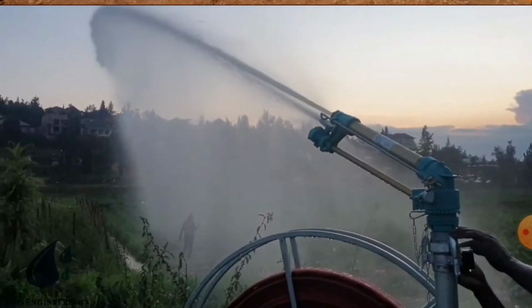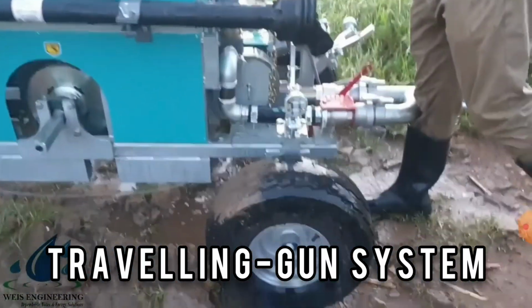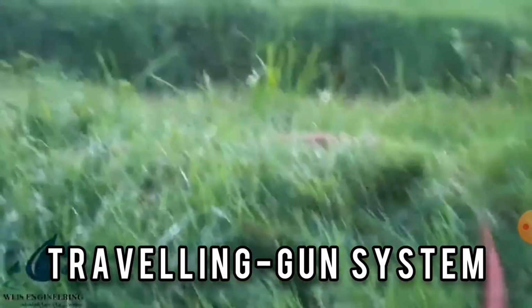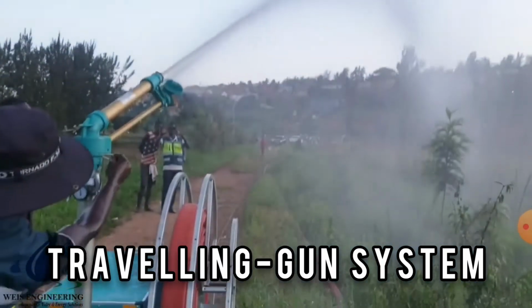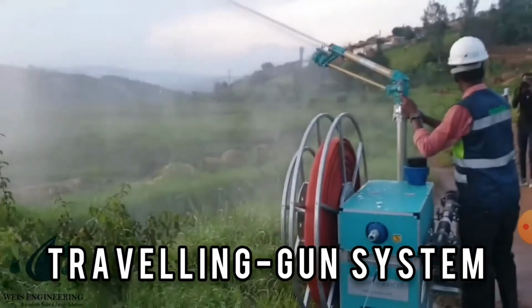The second method is traveling gun systems. These systems are relatively expensive. Labor cost is reduced compared to hand-moved sprinklers. They are well suited to irrigating large fields and tall crops. Uniformity of water distribution is greatly affected by wind conditions.